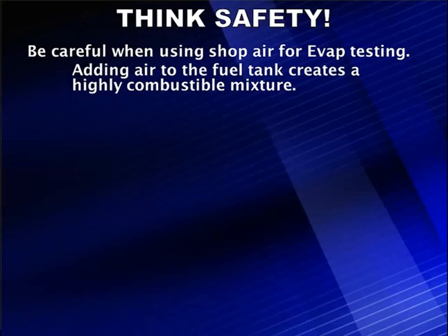Now, think safety for a minute. This is something we have to say. Be careful when using shop air for Evap testing. Adding air to the fuel tank creates a highly combustible mixture. Let's define combustible. Combustible means you have air, you have fuel, and you only need a spark for combustion.